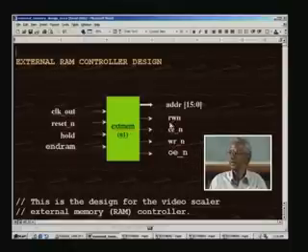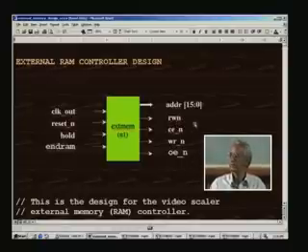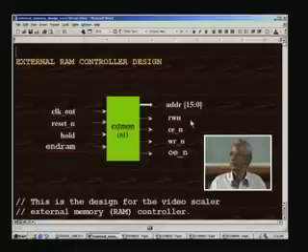And as usual, we have one read, that is a change here. We will make read active high and write active low. So RWN is the one which will select between two RAMs in case we have that. In addition to that, it also serves the purpose of telling us whether we are writing into the RAM or reading, and we can use it in the test bench appropriately here. And there is also an address bus of 16 bits, that means it can address an external RAM of 64 kilobytes. For higher memory requirements, you need to jack this up here.